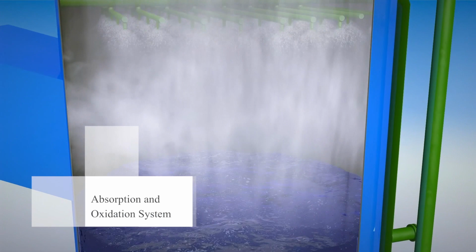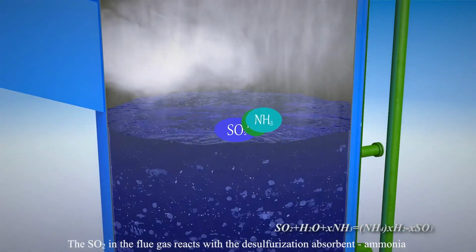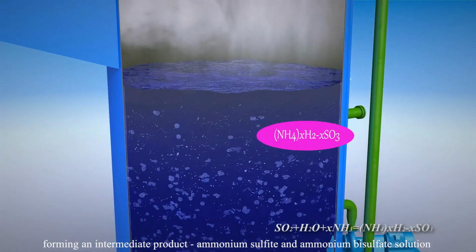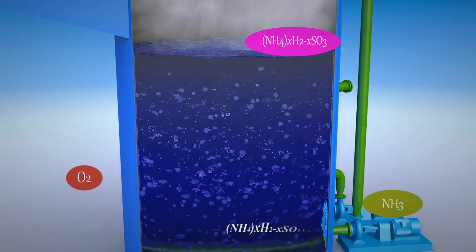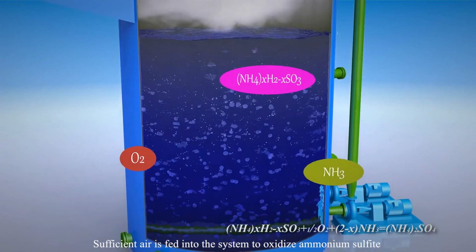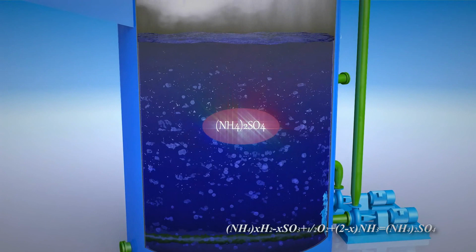Absorption and oxidation system. The sulfur dioxide in the flue gas reacts with the desulfurization absorbent, ammonia, forming an intermediate product, ammonium sulfite and ammonium bisulfate solution. Sufficient air is fed into the system to oxidize ammonium sulfite and ammonium bisulfate to ammonium sulfate.